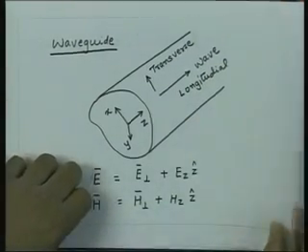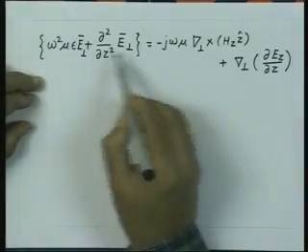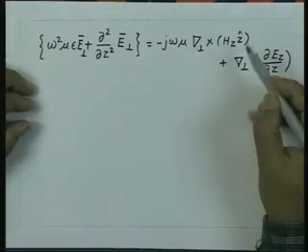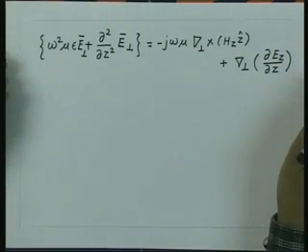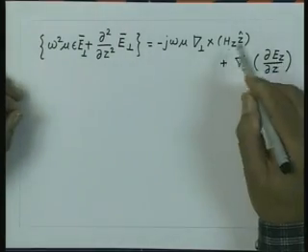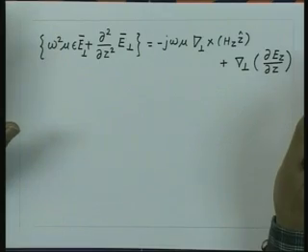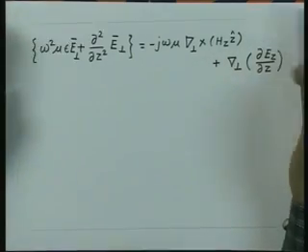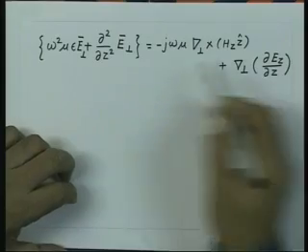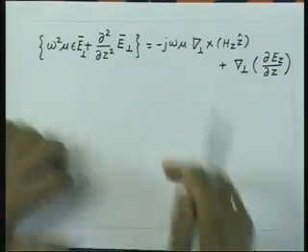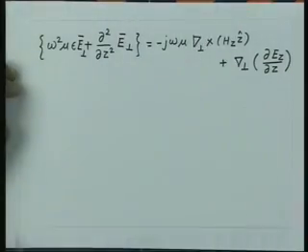We now got the expression for the transverse field in terms of the longitudinal components, which are Ez and Hz. So, we treat Ez and Hz as the independent components, and solve essentially finally the problem for Ez and Hz. Once we get Ez and Hz, then we can find out the transverse field components by using this relation.